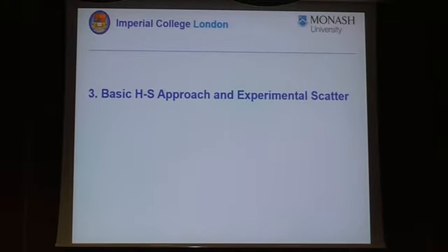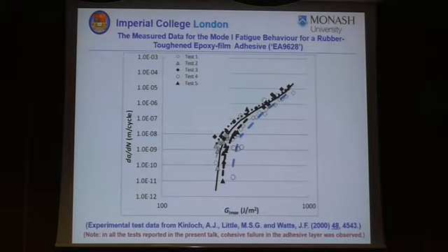So if we look at some basic data, here's some da/dN data for adhesive joints, obtained actually by myself and some colleagues some years ago. We then use G1 max. What I'm showing here really is 5 replica tests, and just notice the scatter. This is the classic da/dN against G1 max. At the time we thought we were doing the right thing. All the failures, by the way, are cohesive failure in the adhesive. There's no delamination failure in this talk.